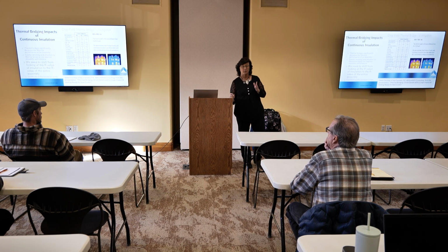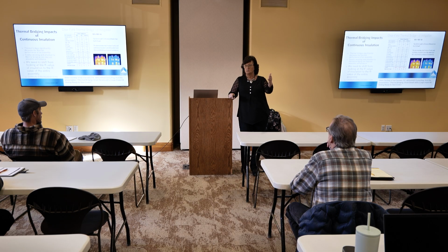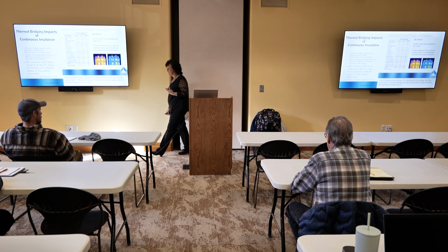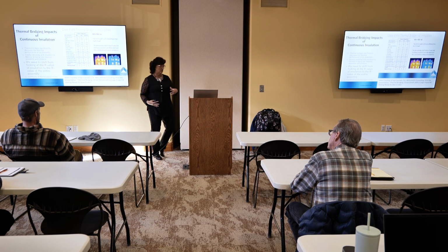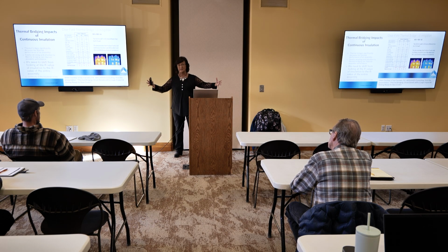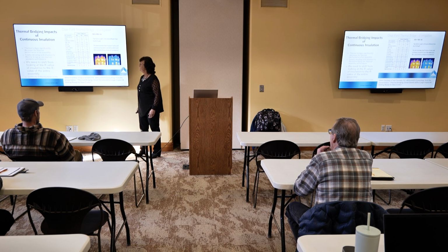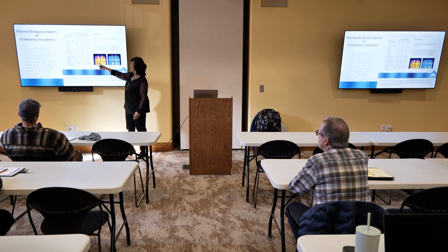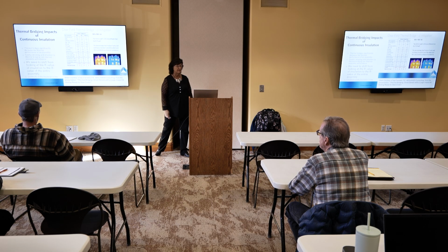It used to be, in the 21 and before, you had the R value table or the alternate U factor table. In the 24, you have the U factor table and the alternate R value table. It wants you to start thinking of the entire assembly and how it goes together. And you want to think about that too as we get into wildfire and how it makes us build, and dew point and how we have to do that. We need to be looking at every layer and how it all affects each other, not just throwing stuff at it. But you could see, I didn't have continuous insulation, and then I do have continuous insulation. A huge difference in the overall effect on that building.